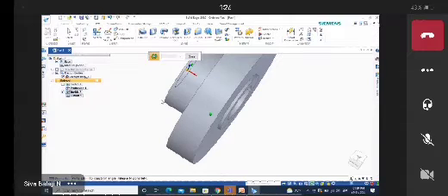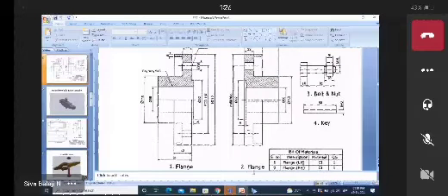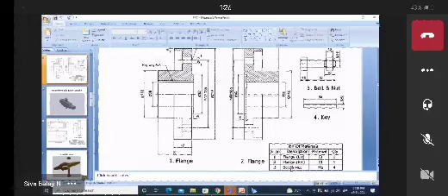Now we have to prepare this flange one part. We have to create holes here. Okay, in the 2D diagram you can check that for fixing the nut and bolt, you have to create holes here. The bolt and nut are given in mild steel material, and more quantity is there. So we have to create 4 holes here. You have to create the 4 holes first, then prepare the nut and bolt. Okay, for this one the diameter is 16 mm. Diameter 16 mm is given.